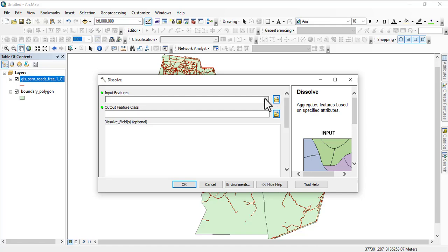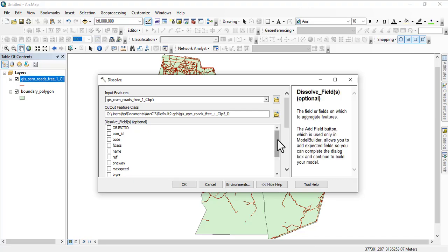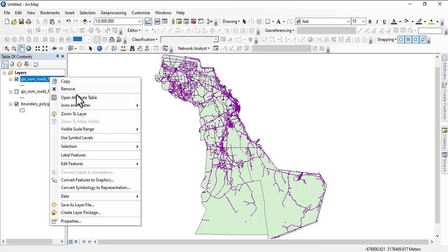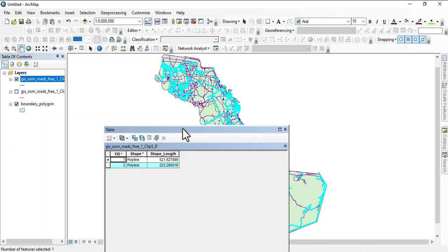So we just dissolve the one we created, and I'm not going to hold it to any field. I'll leave everything the way it is. So I'm just going to dissolve. Once it's dissolved, we'll continue from there. What happens whenever a file is dissolved is that it all stitches together, right? All of the features are merged into these two. Now we don't have any attributes aside from the shape length and all of that.